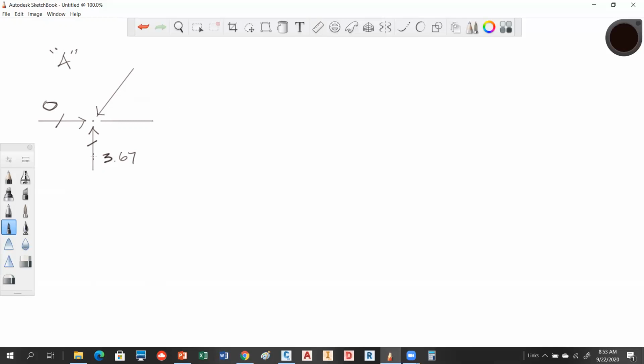But if you look at this guy in that diagonal, this guy has to be going down because that's going up, and that can contribute nothing to that. So I'm going to call that member AB. That member AB is in compression because remember, joint B is up here. And if this guy is going this way, this guy has to go this way. So again, if you don't see what I just did there, don't worry about it because the math is going to tell you what's going on there, okay?